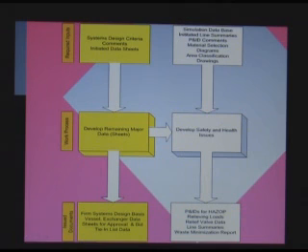And we also incorporate the client comments from the approval issue. Okay. So the next issue is now the familiar word already. We go out for HAZOP. So P&IDs get issued again, and the HAZOP issue is the one that undergoes the HAZOP review.